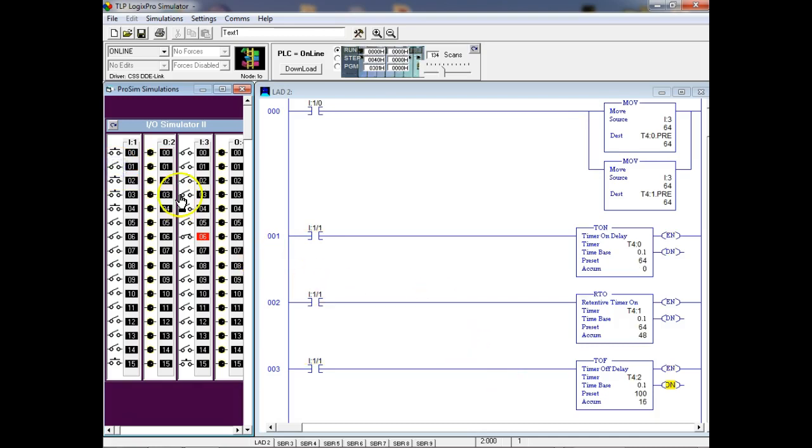Oh, I'm sorry. There we go. So notice when we come up here and we enable it, when the rung is true, now we're talking about the off delay. Let's go look at that. So you're right, I'm sorry, it's a non-retentive. But if the rung is true, what's my timer doing? Nothing. Right, you understand? Because it's not an on delay timer, it's a what? Off delay timer. So what the off delay timer is looking for, it's looking for this rung to become what? False.